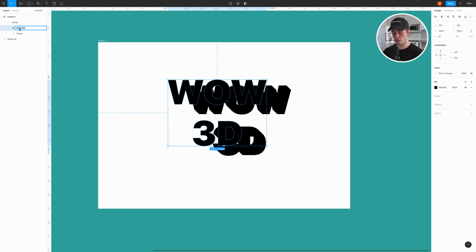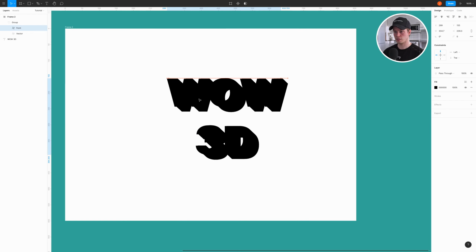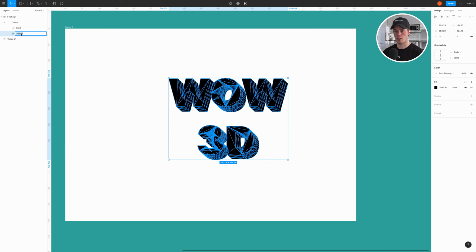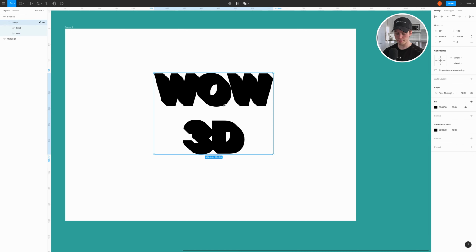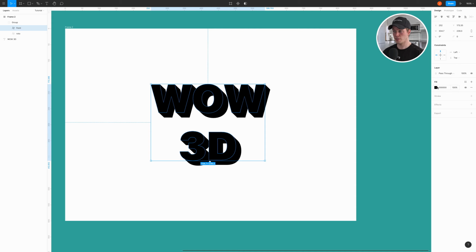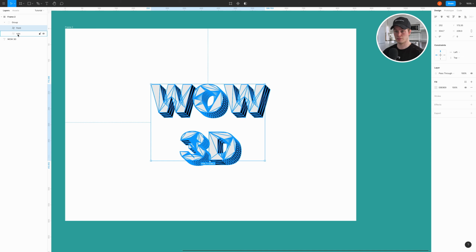This is going to be the front of the text, so let's name it front, and align it with the new extruded text layer. Let's also rename this to Roto, so we know what is what. Let's center this, and if this is all you need, you're basically done.